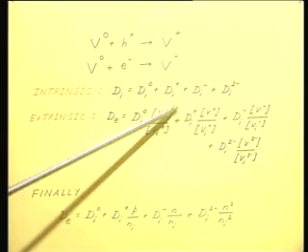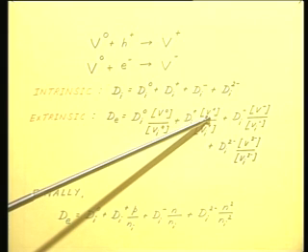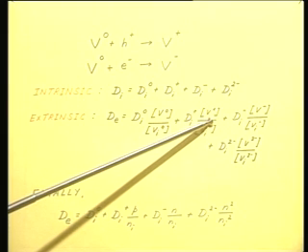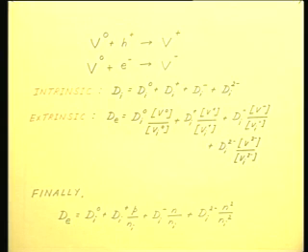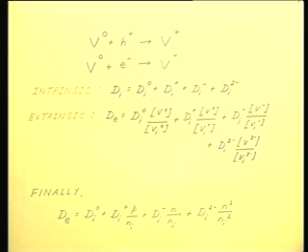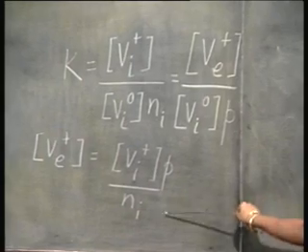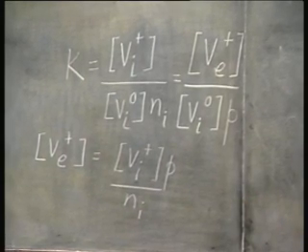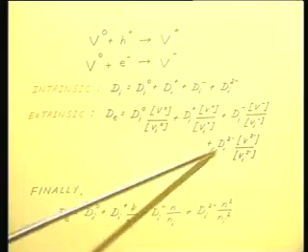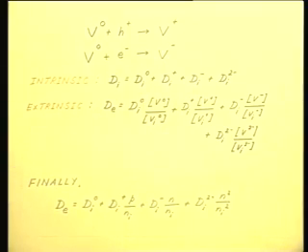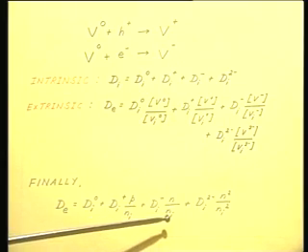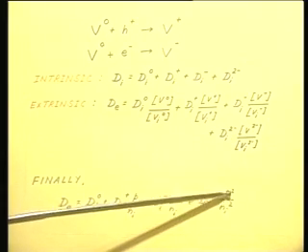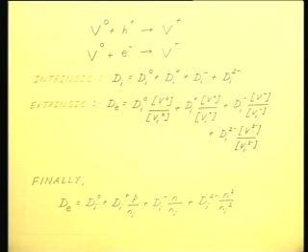In the second term, what happens? This is my extrinsic positively charged vacancies, this is my intrinsic positively charged vacancies, and their ratio is given by P by Ni. So, I can replace it by P by Ni. In this third term, this ratio is going to be N by Ni, and in the fourth term it is going to be N square by Ni square.